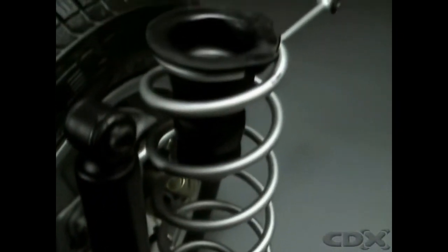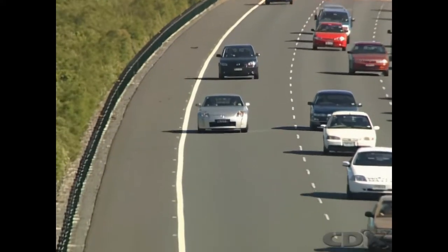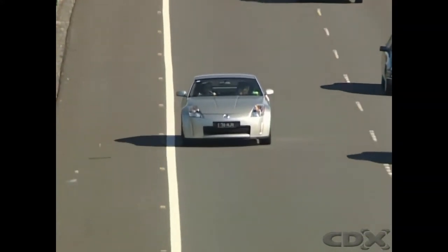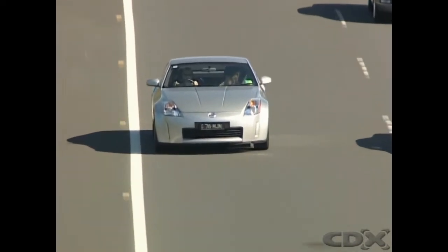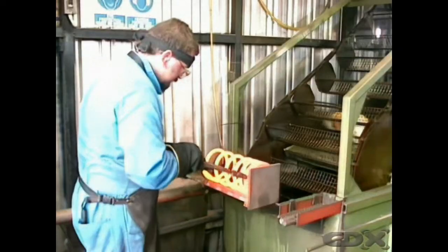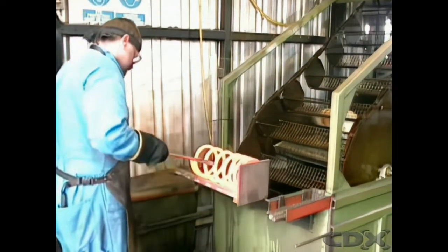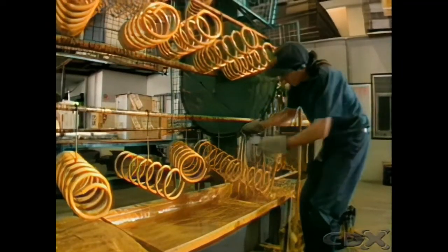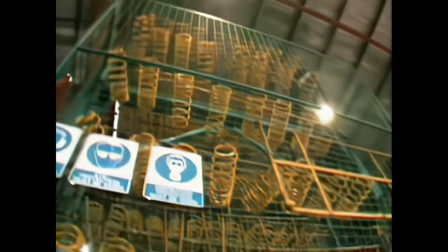Coil springs are used on the front suspension of most modern light vehicles, and in many cases they have replaced leaf springs in the rear suspension. A coil spring is made from a single length of special wire, which is heated and wound on a former to produce the required shape. The load-carrying ability of the spring depends on the diameter of the wire, the overall diameter of the spring, its shape, and the spacing of the coils. And this also decides which vehicle it is suitable for.